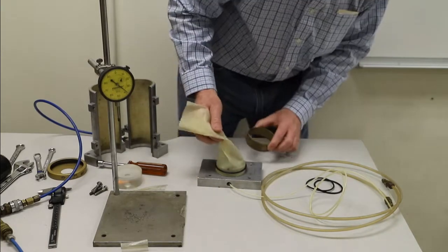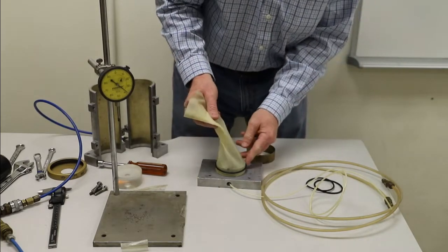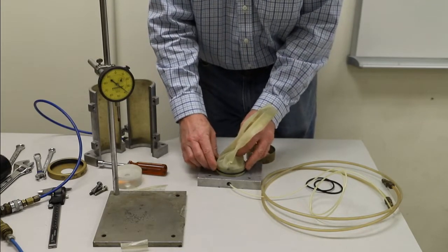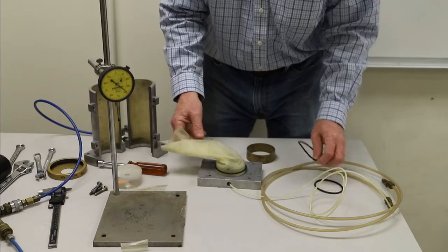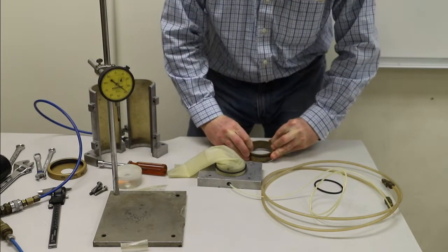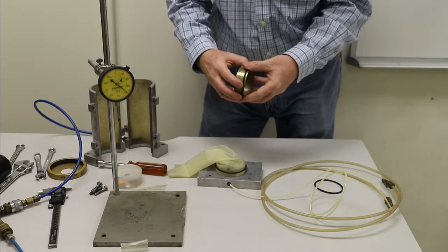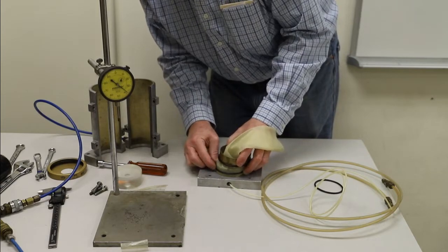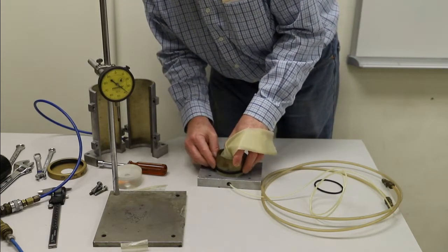It's pulling the membrane tight against the cap, and again, that's going to be a seal that ensures we can have different pressures between the outside and the inside of the sand sample. I'm going to put on 2 here just for good luck. It's more of a superstition than anything else. There's no real reason we need more than 1.